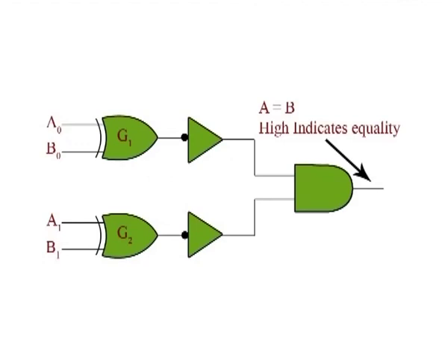In order to compare binary numbers containing 2 bits each, an additional exclusive OR gate is necessary. The two least significant bits of the two numbers are compared by gate G1 and the two most significant bits are compared by gate G2 as shown in here. If the two numbers are equal, their corresponding bits are the same and the output of each exclusive OR gate is a 0. If the corresponding sets of bits are not equal, a 1 occurs on that exclusive OR gate output.